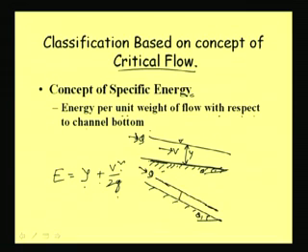So now if I say it is y2, I can again use an index. Suppose in this case it is y1, v1, and here it is y2 and it is flowing with a velocity v2. So for the same discharge, if I increase the slope, the velocity becomes v2 and depth becomes y2, and for this it has energy E2 is equal to y2 plus v2 square